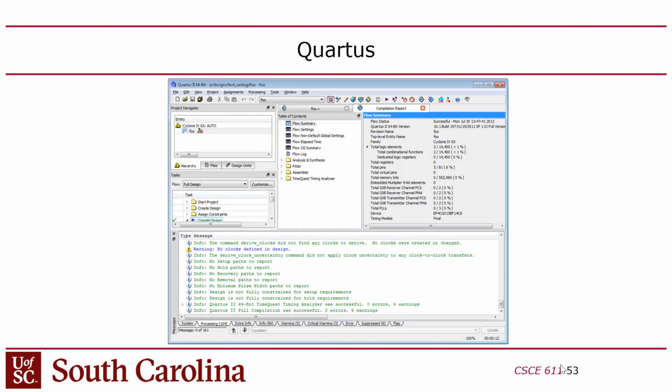I mean, I can put this circuit on the FPGA, but there's no way to access it from the outside world, so I'll just delete it. And that's exactly what it does. So you'll compile it, and it'll say 0 LUTs. And you're like, what do you mean 0 LUTs? I put a whole CPU on there. Yeah, well, it optimized it out, right?